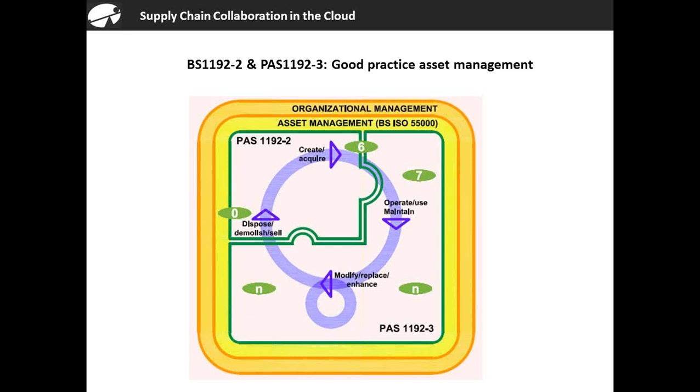Now, these are essentially British standards. BS 1192, I believe, is a British standard that establishes methodology for managing the production, distribution, and quality of construction information. That includes information generated by CAD systems. And PAS 1192 focuses on project delivery, where basically the majority of graphical data and non-graphical data and documents is collectively known as project information model.